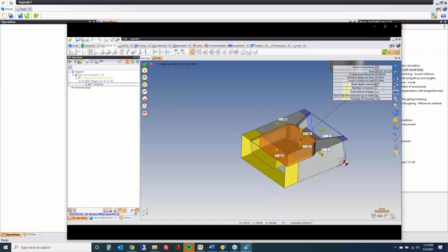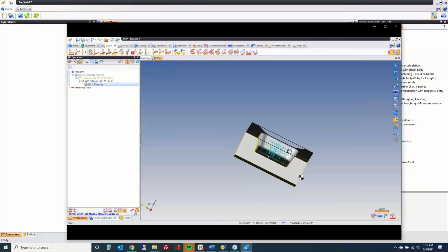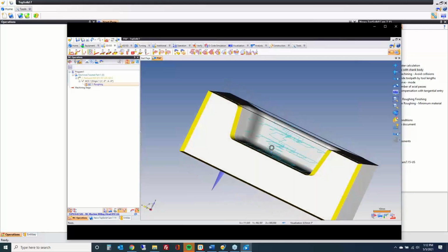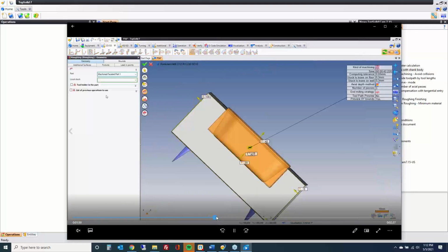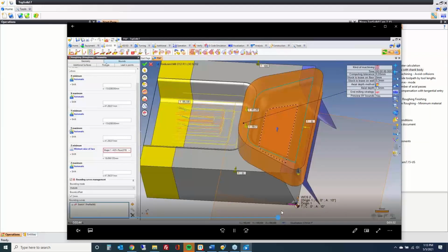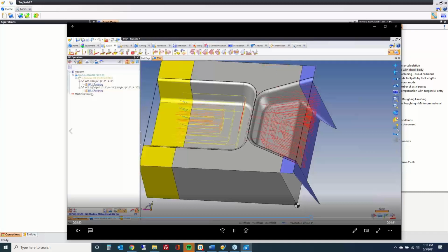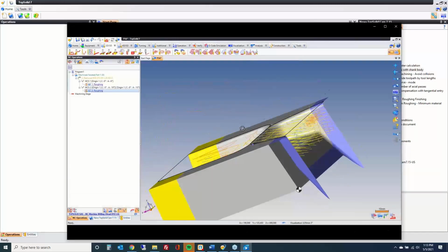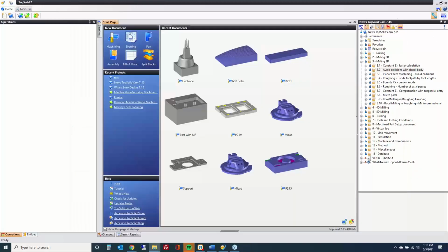We're going to change to number of passes. So if we say we want 3 passes, the software is going to calculate automatically from the maximum altitude to the lowest altitude and just divide it by 3. Just like you saw in 2D milling, you have that option in 3D machining as well. Is there anything else that is important in this? Nope, we're good.